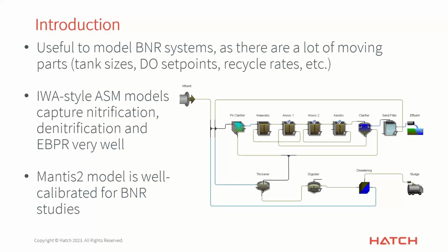I mean, that's exactly what they were designed to do. So those approaches have been tried and tested and well calibrated over the years to be able to accurately switch to different types of growth depending on what the conditions of the reactor are, whether it's anaerobic or anoxic, for example. And also we have really good understanding, I think now, of what types of biomass are growing under what conditions and what the stoichiometry of those things are. So the models are really useful for doing that type of design.